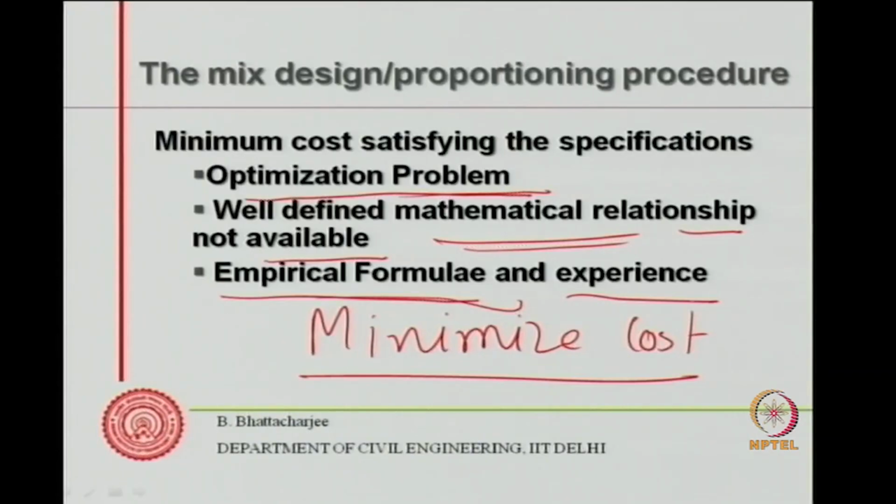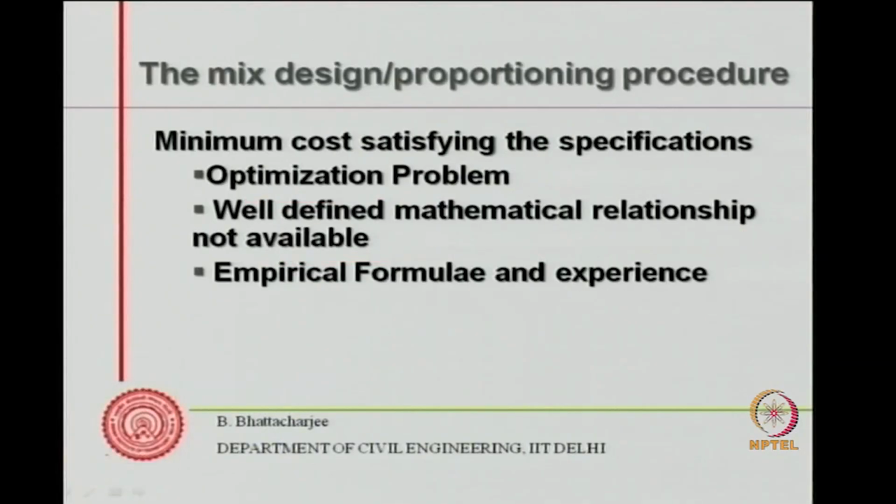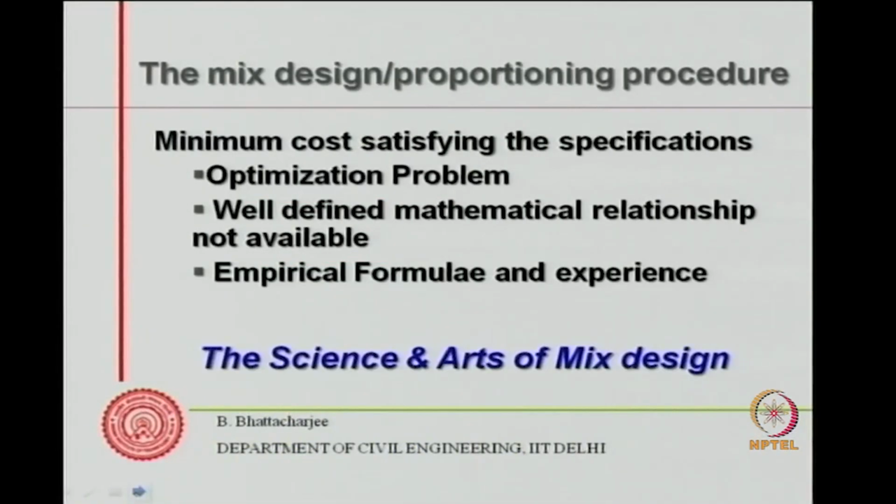Therefore, we can't formulate it as a mathematical problem. And even if we do, it will be case specific. So the use of very sophisticated software, etc., really doesn't make sense at the moment. They are not very conducive. In fact, finally you have to make a trial mix. So we must understand that the mix design procedure is largely empirical in nature, and it is not only science, it has a large art component.